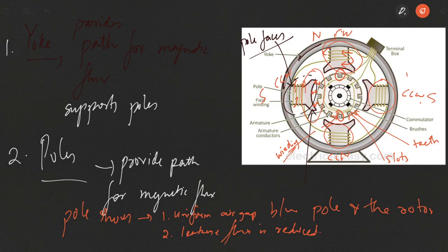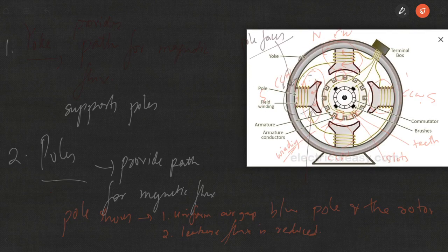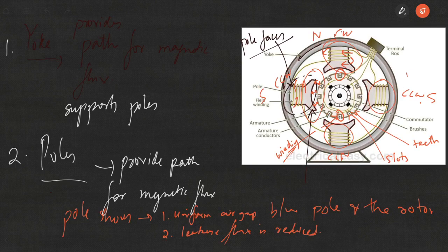They are actually conductor bars. We place conductor bars in these slots, and then we connect each and every conductor bar so as to complete the circuitry of the armature windings. So these conductor bars placed in the slots of the armature are connected with each other. So you can have this conductor connected here, connected here. So each and every conductor will be connected in a different manner with the next conductor, so as to form a complete circuit.